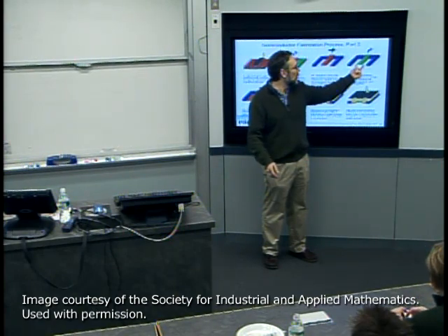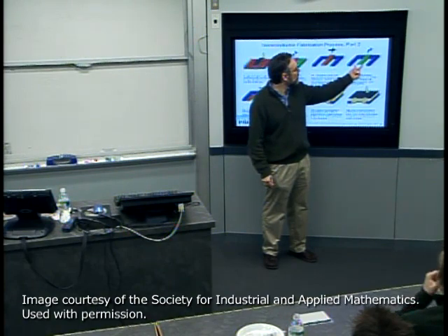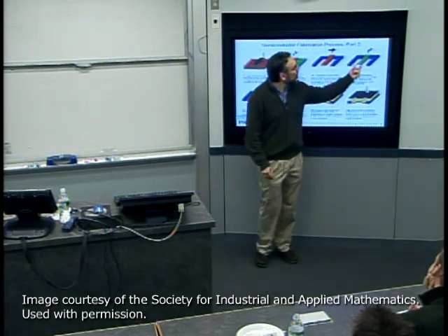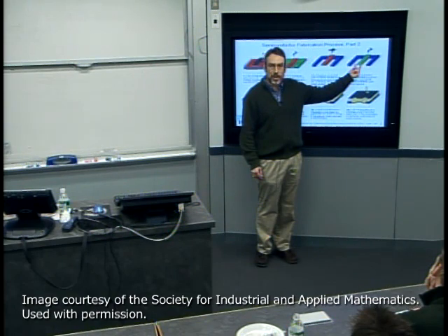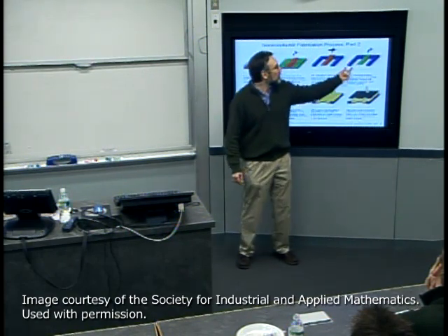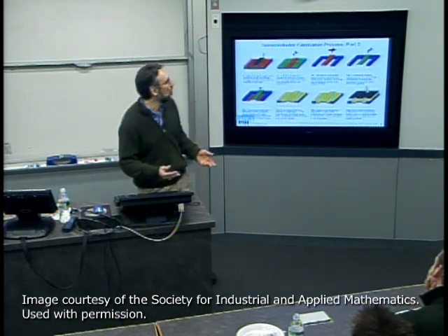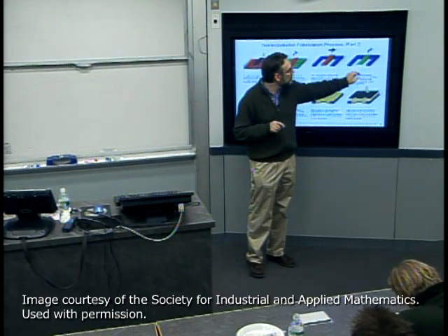We're getting close to these velocity limited transport regimes. And so from one point of view, the speed of the transistor is critically dependent on variations in that channel length. This is often referred to as the CD or one of the CDs of the process, critical dimensions of the process.